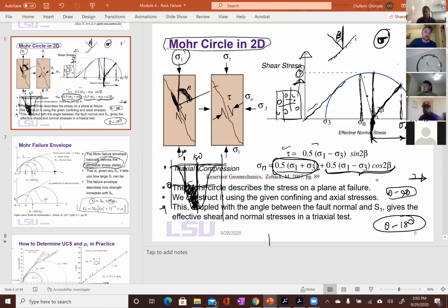And again, if this rock has pre-existing cracks in a certain direction, then it will fracture along that direction instead, right? Because you have pre-existing cracks. So that's one thing you will see as we go further in this topic. There is frictional sliding for an intact rock, which has no fracture, no pre-existing crack. You want to create a fracture, it's always going to fracture at 60 degrees in this normal faulting regime we have artificially created in the lab. Then there are rocks that already have pre-existing flaws in them, and those pre-existing flaws weaken the strength of the rock, and those behave differently.